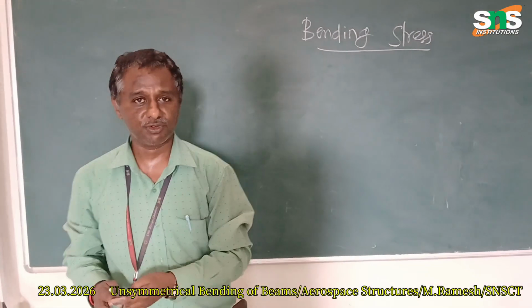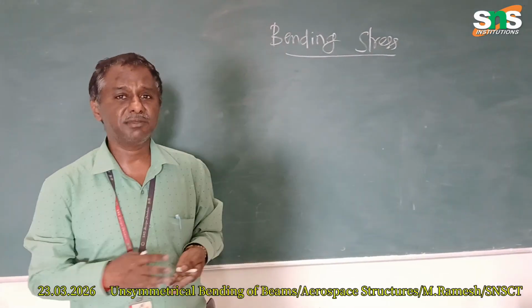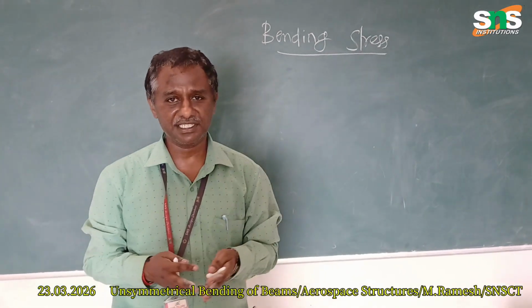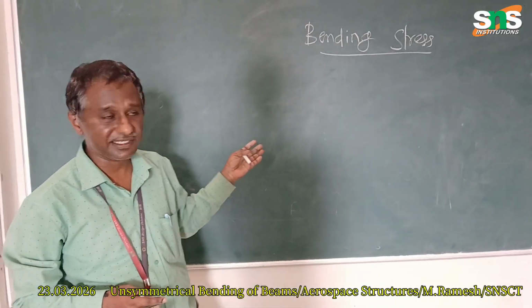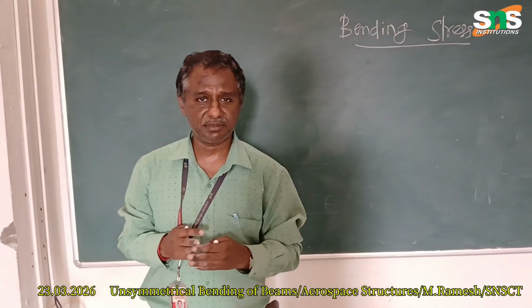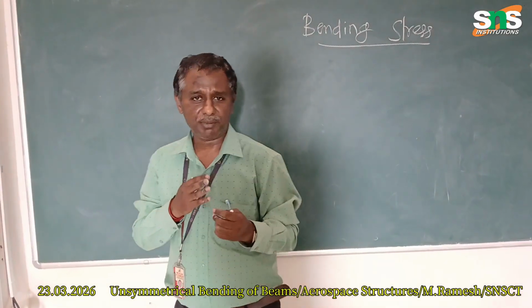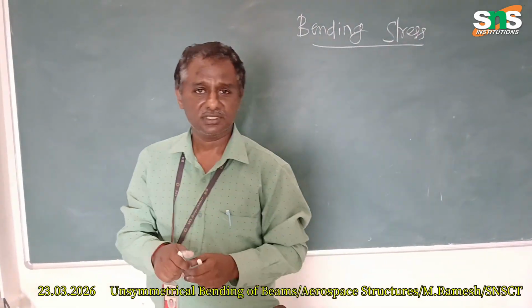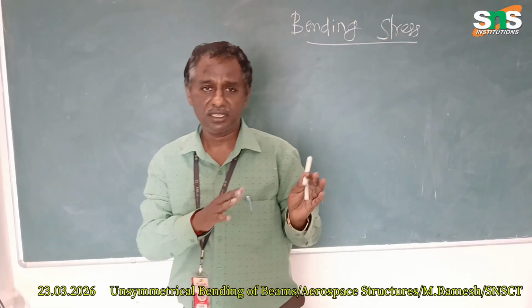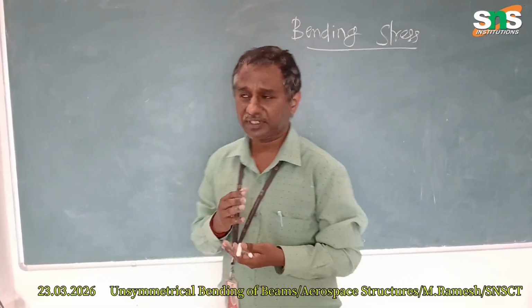We are going to discuss the bending stress for unsymmetrical bending of beams. That comes under the second year students' aerospace structures class. First, we should understand what symmetrical bending is as well as unsymmetrical bending. If you apply a load on the surface of a beam, and the bending happens parallel to the surface of the beam, that is called symmetrical bending.